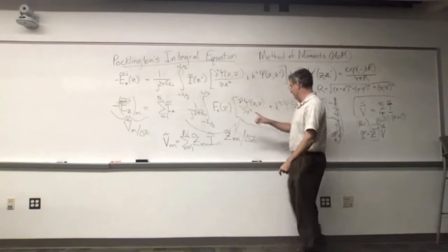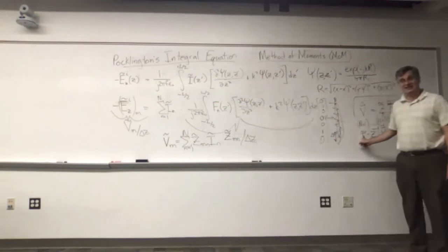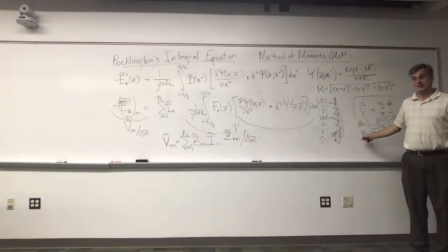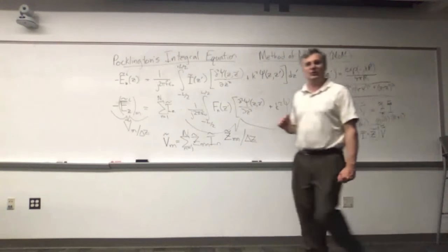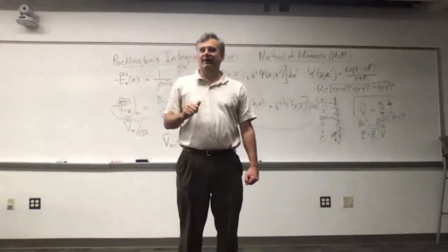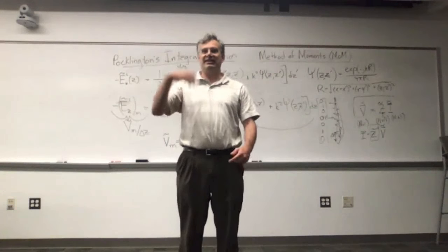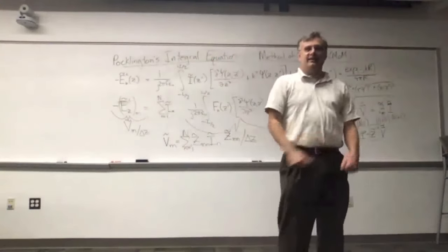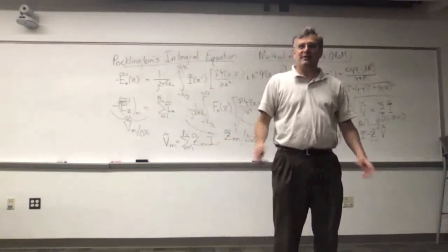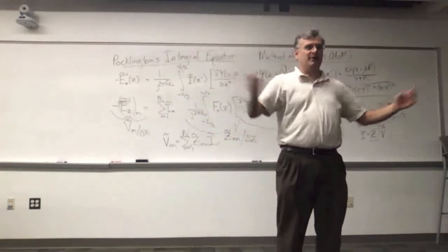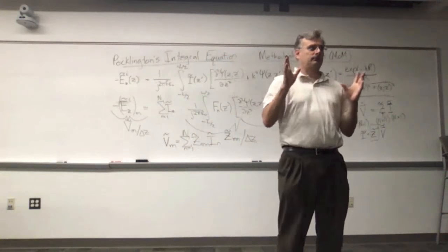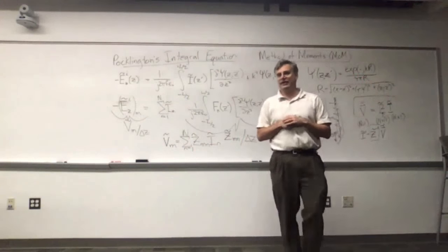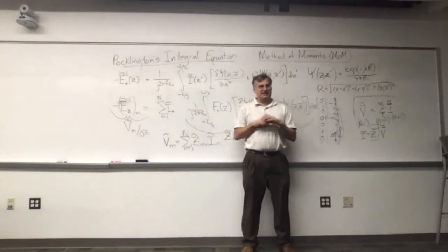Once we solve for this, our work technically isn't done yet, right? I still now have to take this and put this into the vector magnetic potential equation, and then calculate E's and H's and Poynting vectors and integrate to get total power, use that to calculate gain, and keep on going and going and going. That's the full gamut of what an electromagnetic solver can do.